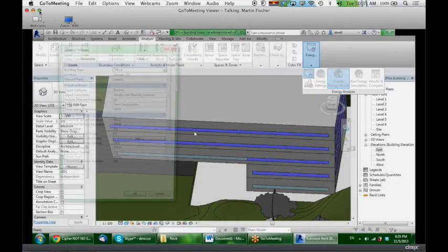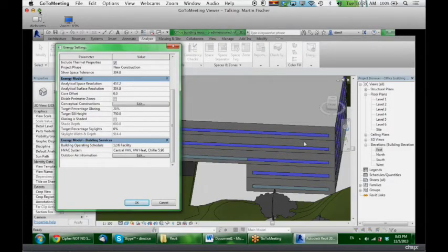I will show you later how we can customize the glazing area for each of the building surfaces, but for now, this is the default approach. You can also play around with the sill height for each of those surfaces. Right now, it's set to almost a meter high, but you can make it higher, and you see that they moved up a bit.